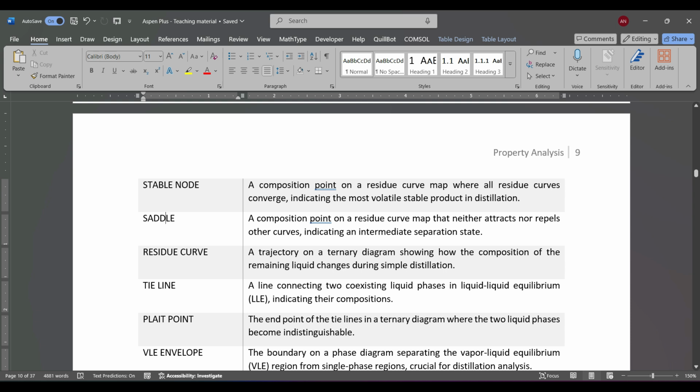So if we have a Ternary system in a single liquid phase, and we operate a distillation for that single liquid phase, how the liquid in the reboiler and the vapor in the condenser, those compositions vary at different temperatures, or at least the line connecting these two compositions between condenser and the reboiler, that line is the residue curve.